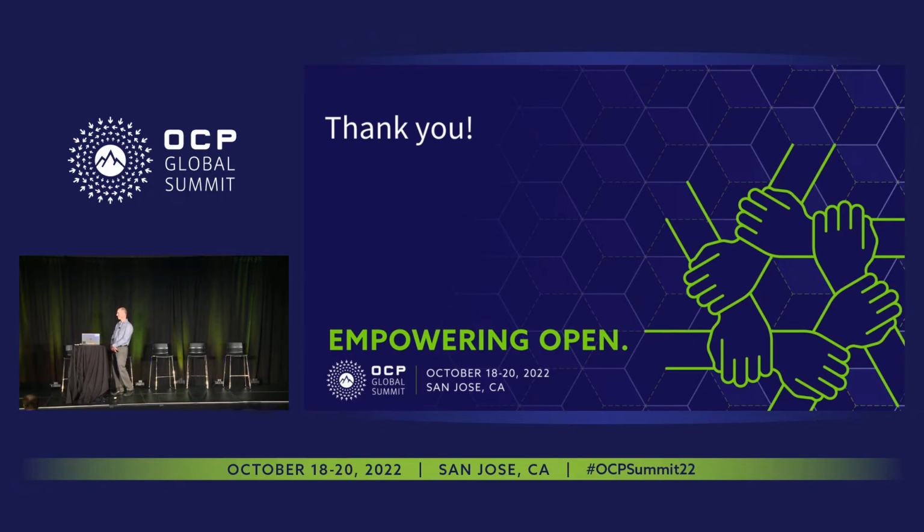People are shy. So the requirements for the data center, can you elaborate more, like what we have so far in terms of environmental things? Yeah, we have 3 requirements that I discussed: the Grandmaster, the transparent clock, and the ordinary clock. The Grandmaster clock requirements are typically satisfied by an atomic clock today. And we want to expand that into an OCXO for a POPs environment, the point of presence servers. Today, we just have the Grandmaster for the hyperscaler environment.